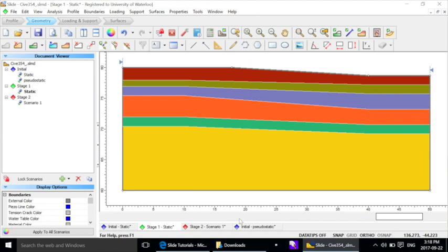We now have two scenarios, and we have different stages, and we are going to start with excavation in this stage and this scenario. For that scenario, we are going to add these vertices. We need to include here the boundary. Remember this one, which is 30.68. So this is the constraint for the excavation. Now we add some of these boundary vertices, and it's very simple.